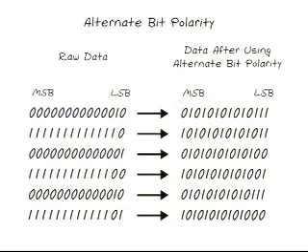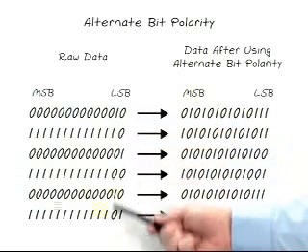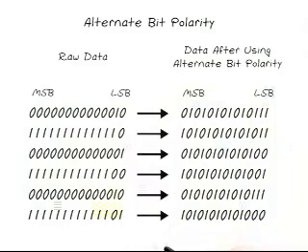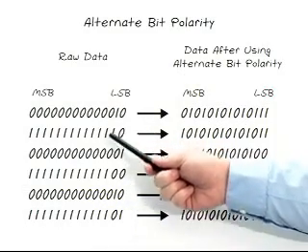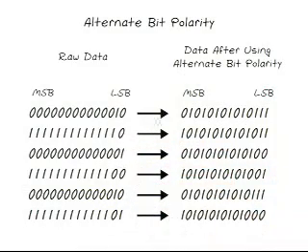In this example, we have a signal that is exercising a few codes around mid-scale. On each sample, all of the high-order bits are swinging from 0 to 1, which generates large ground currents that can couple back into the analog input, maximizing digital feedback.